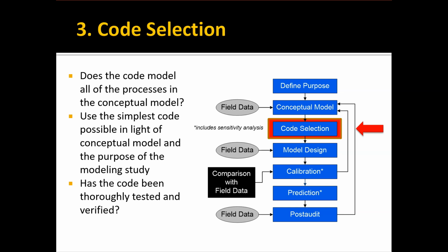So if you're going to use something other than MODFLOW, it probably has to be a fairly unique set of circumstances. Maybe you have some special condition that MODFLOW doesn't have the ability to simulate, and so you have to use some more advanced code. Those cases are getting fewer and fewer. There are so many options built into MODFLOW by now that it's quite rare that you encounter a scenario where MODFLOW won't work. On the other extreme, sometimes you will see a number of analytic element models used, and we'll talk about those a little later in the semester if I remember.